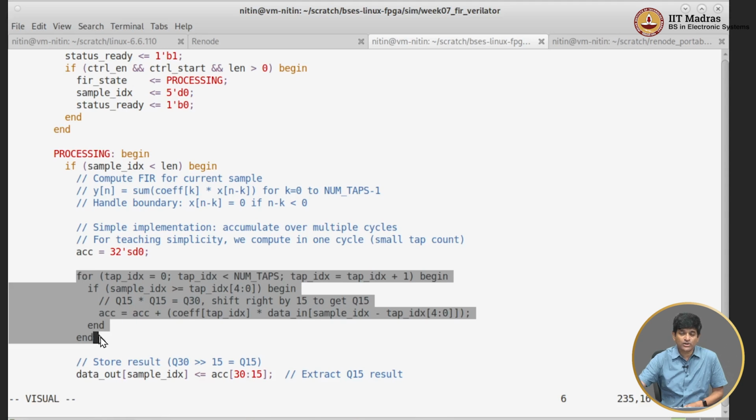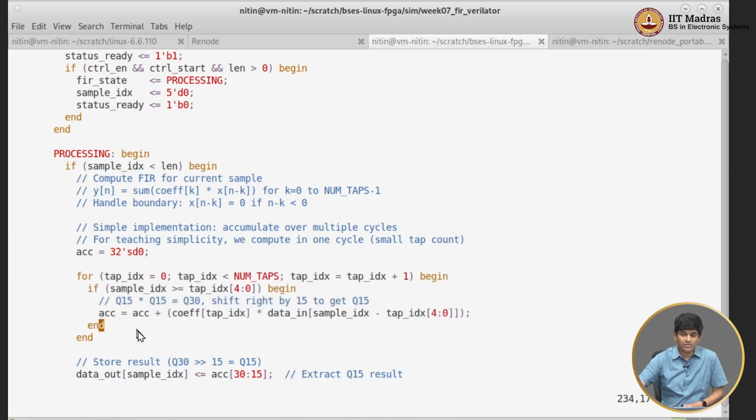I said, if you were actually implementing in hardware, would get unrolled into a single computation of 4 multipliers and the corresponding additions. For a small enough number like that, it is actually also practical, it's not very difficult to do, so it might be a good way of implementing an averaging filter.